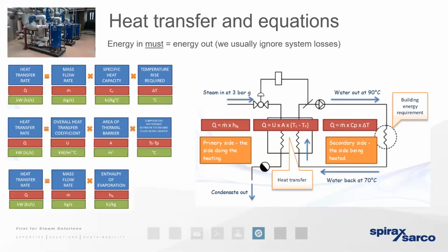In the case of a shell and tube heat exchanger, it would refer to the surface area of all of the tubes that were involved within that bundle, that tube nest. Again, the A value, the area, that will typically be badged on any existing heat exchanger. We can find it from the thermal energy data sheet of the manufacturer, or again, we can go back to first principles and we can calculate it.